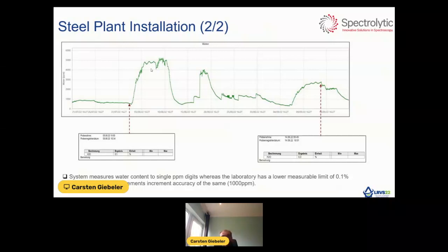One nice way of looking at the data in a different way is you can potentially even use this data to think about failure mode analysis. You can see from this data here, you have one leakage type, which looks like a continuous leak, where you can see there's a water ingress over a period of time, which is here and which is here. Whereas the middle one has a different shape.